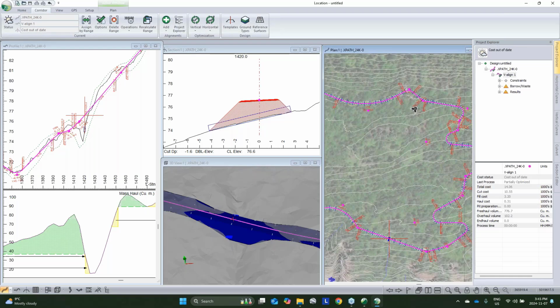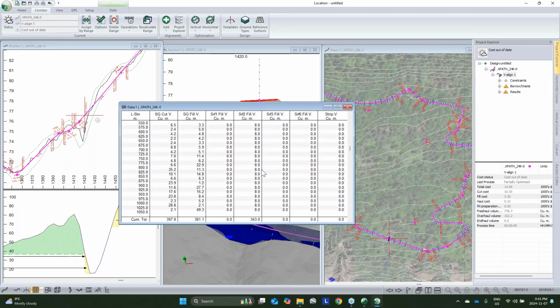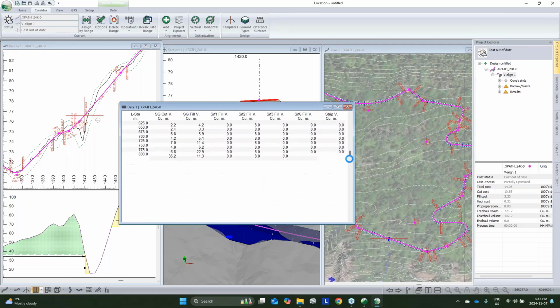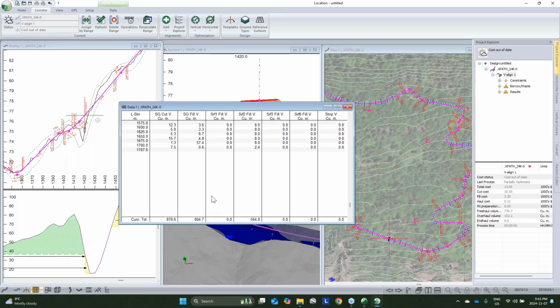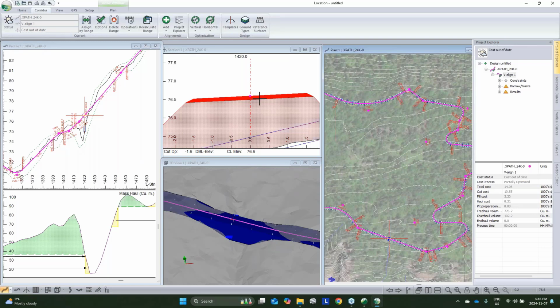Perfect. Thank you, Matt. Do you want to squeeze in a last one that I think is interesting? I really like this question. Can you get a bill of quantities for materials and culverts? Yep. So it's a good one. I've got my volumes here, and I've got them set, and I can come down to the bottom and see what I'm dealing with for my cut and fill quantities. On this one, I do have a surfacing layer included. So I've got 500 cubes of gravel for that 10 centimeter lift. If we changed it, everything would update.